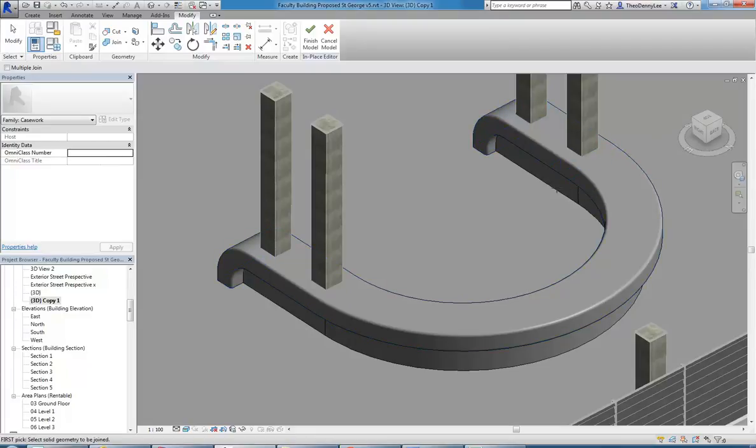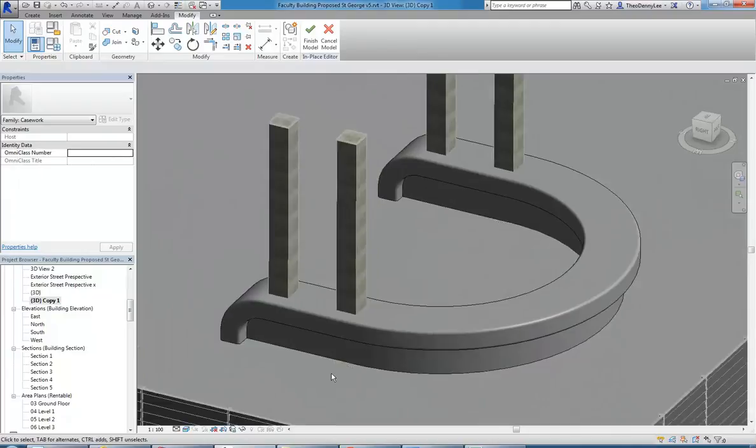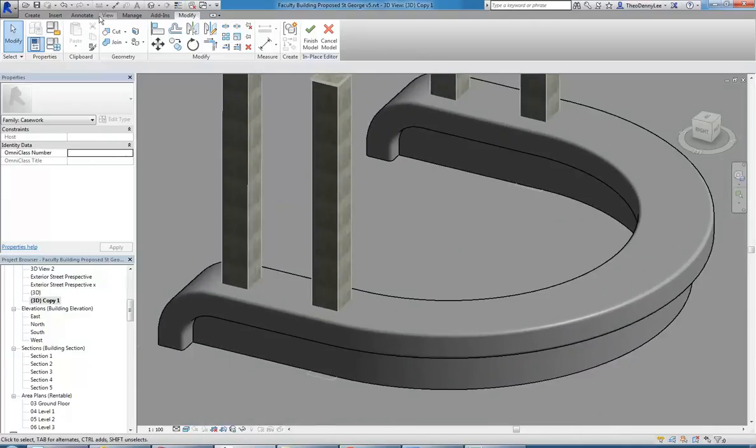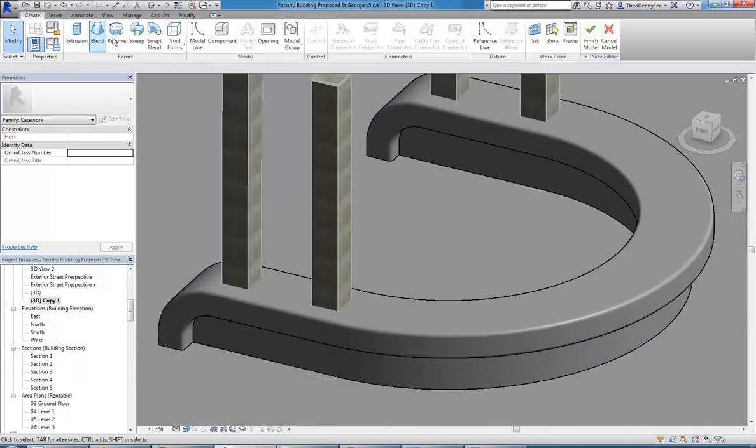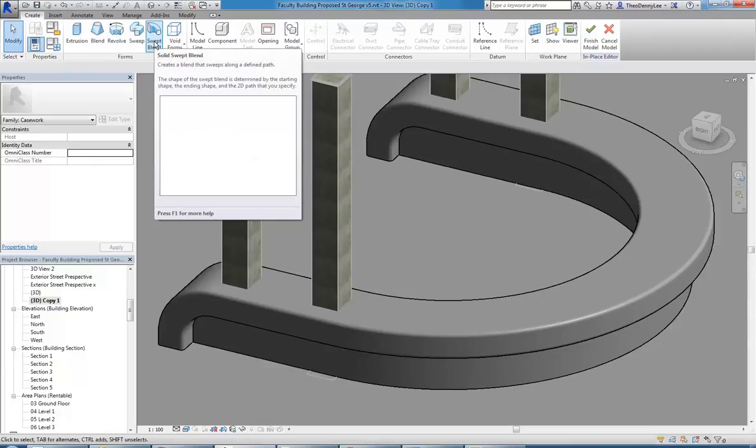And that's often the key to modelling complex forms. Massing and all those other options are great, but in many cases you can get forms that obviously are possible with these tools on their own just by combining them. So combining a sweep and a revolve, you can get things that take a profile into different planes, like you have there.